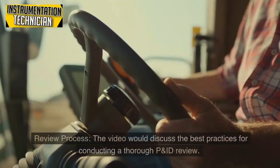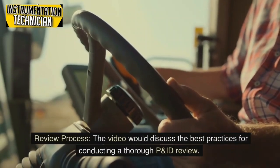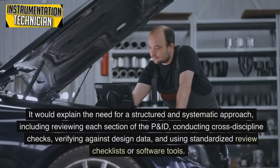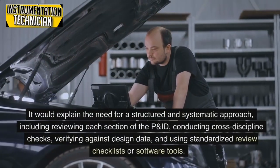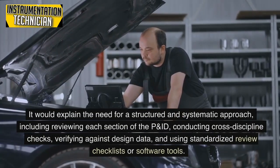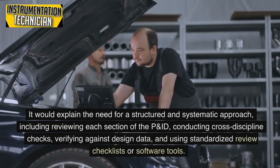4. Review process. The video would discuss the best practices for conducting a thorough P&ID review. It would explain the need for a structured and systematic approach, including reviewing each section of the P&ID, conducting cross-discipline checks, verifying against design data, and using standardized review checklists or software tools.